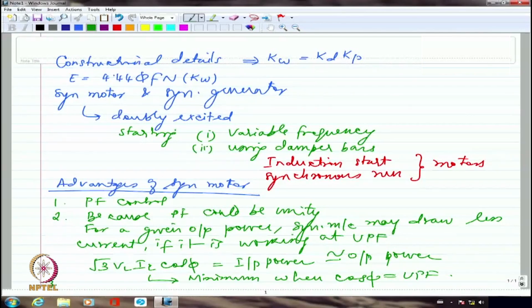It will rotate normally about an axis, but there may be a little torsional motion which may go and hit the stator if there is not enough leverage or enough margin available. So in the case of a synchronous machine, I would be able to use those synchronous motors even in those loads where I may expect some amount of torsional motion or some amount of vibrations in the rotor.